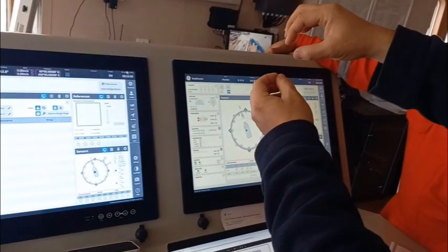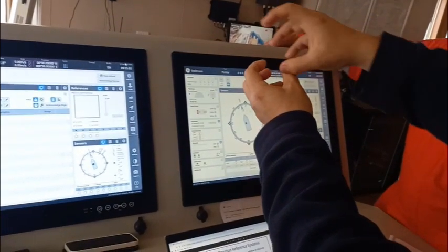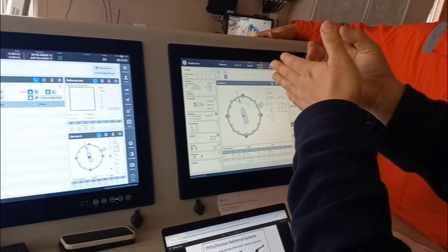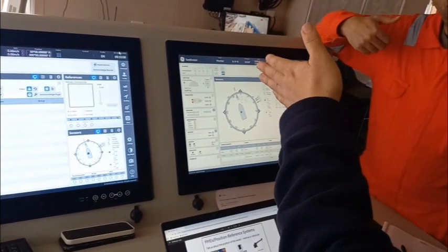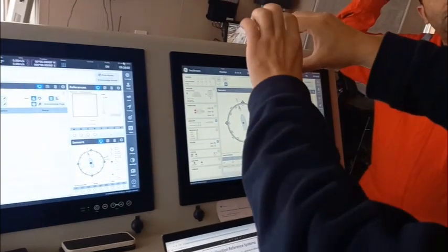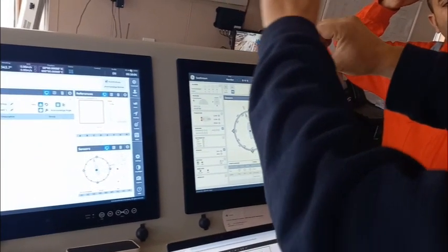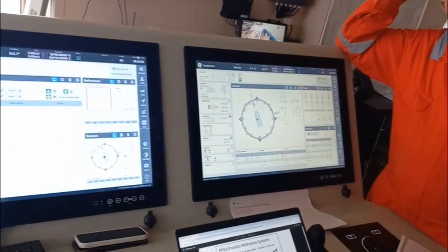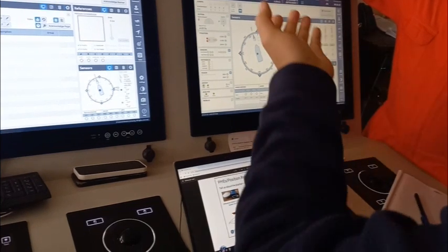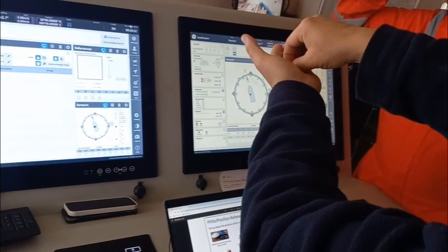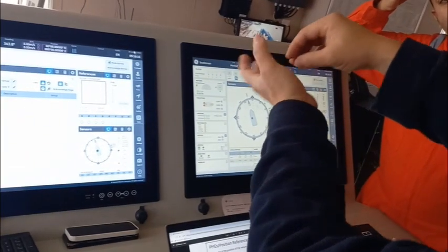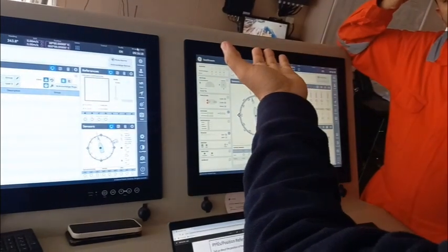Then there is a contact there sending the connecting signal, a contact signal to DP, to show the DP this gangway is connected to the third vessel. Yes, it's actually a contact or switch. When it is deployed, this switch will be pressed and then send a close signal to DP.